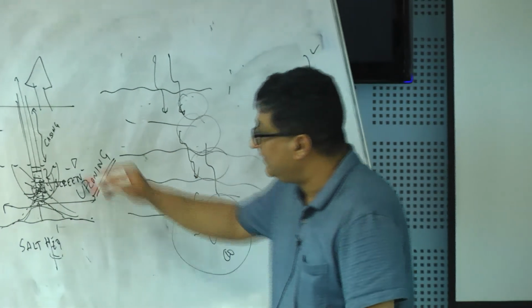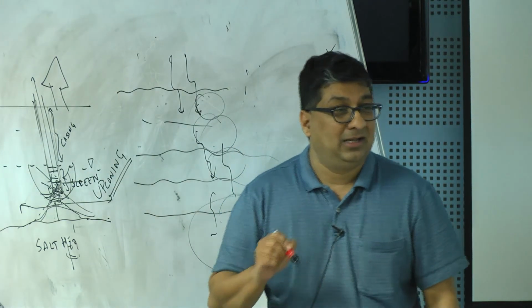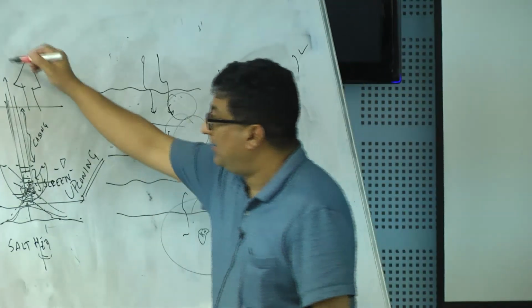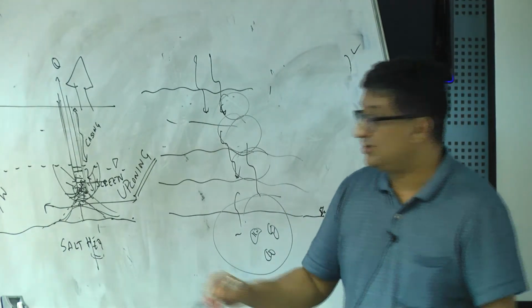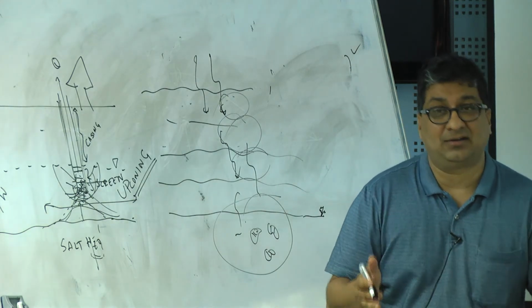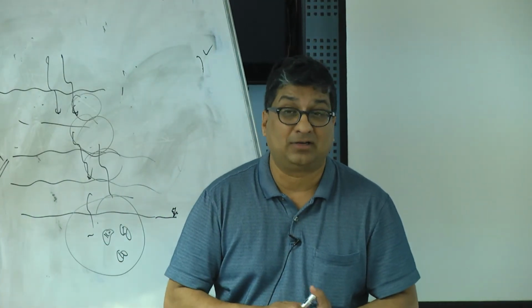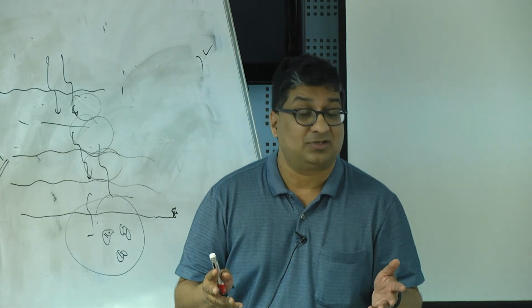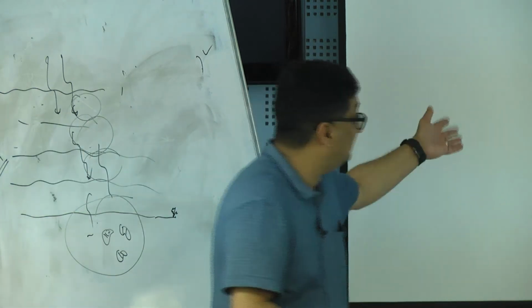So it's not enough that you put a well in the freshwater zone. It's also important how you pump. You limit your pumping, because if you pump too much, you will end up getting salt water. Your intention is not to contaminate that water, but this is a source of contamination. It's a source of contamination because, although it's not your intention, by pumping you have increased the water flow. Okay. So that's the sixth source. So we have 6 types of sources. We have many thousand contaminants.